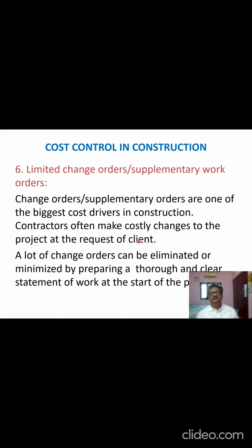The scope of work has to be defined in the beginning of the construction activities. A lot of change orders can be eliminated or minimized by preparing a thorough and clear statement of work at the start of the activities.